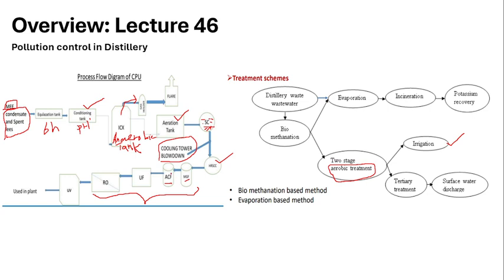So again, the filtration is happening here. And then comes the UF. We know UF is ultrafiltration. First we are using the carbon and multi-grade components for filtering the solid particles, and then to increase the purity of the water, we are filtering it through the ultrafilter. Okay, so ultrafiltration happens. Next comes the reverse osmosis.